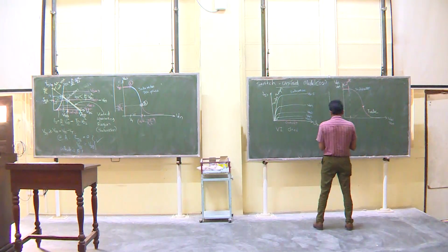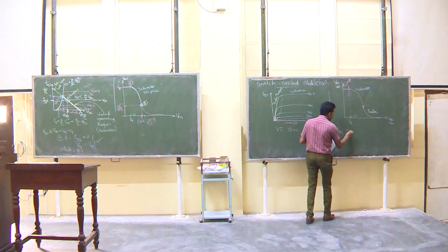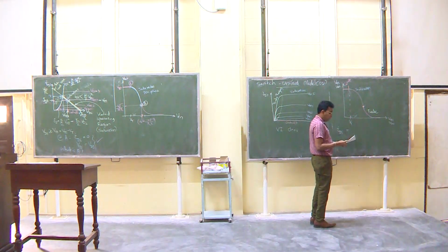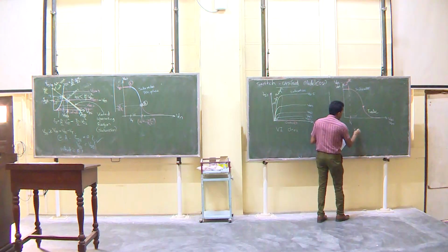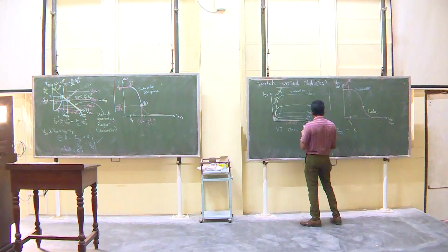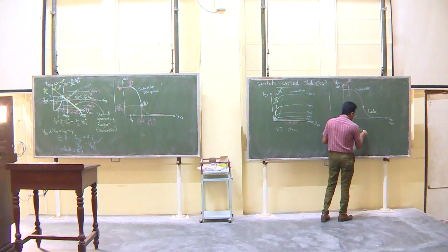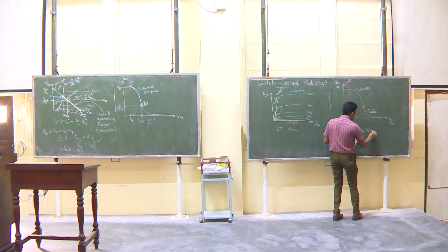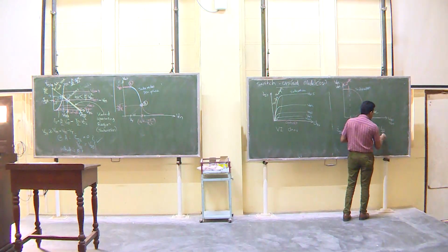Okay. So, if I write a unified equation for IDS, for the triode region, I'm just going to give the equation, but I'm not going to derive it. It will be this nonlinear region. ID versus VGS: K times (VGS minus Vt), that is the overdrive voltage, times VDS minus VDS squared divided by 2.